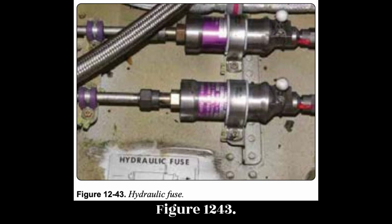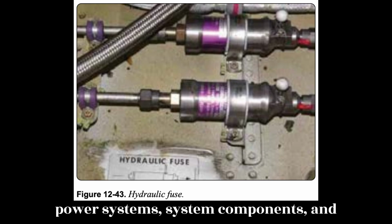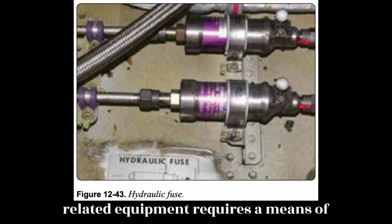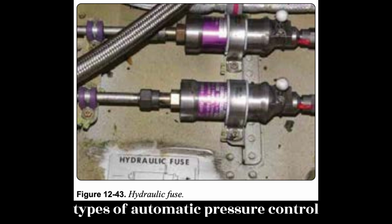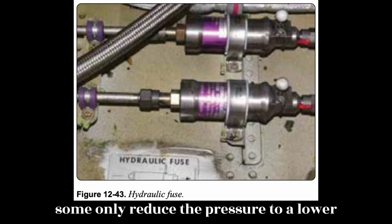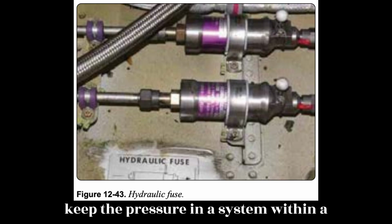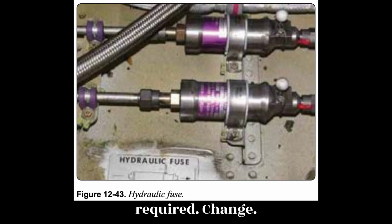Figure 12.43. Pressure control valves. The safe and efficient operation of fluid power systems, system components, and related equipment requires a means of controlling pressure. There are many types of automatic pressure control valves. Some of them are an escape for pressure that exceeds a set pressure, some only reduce the pressure to a lower pressure system or subsystem, and some keep the pressure in a system within a required range.